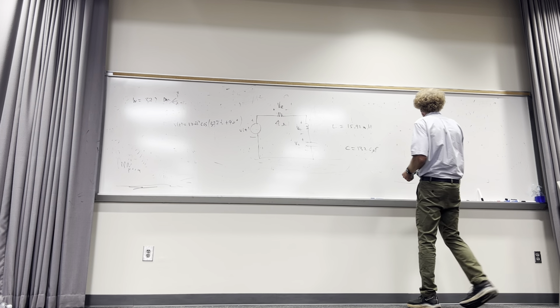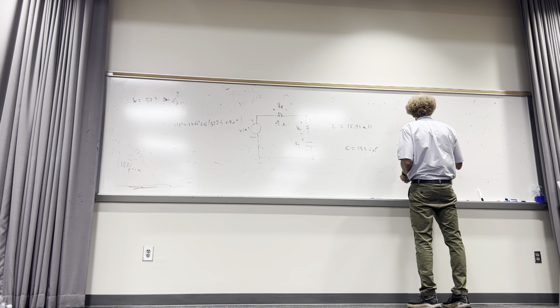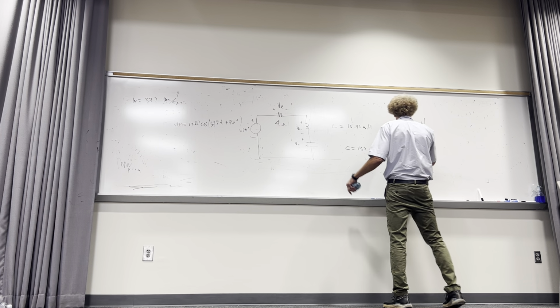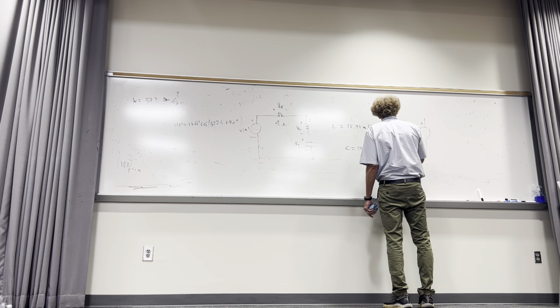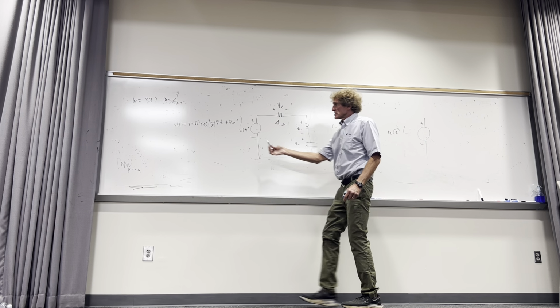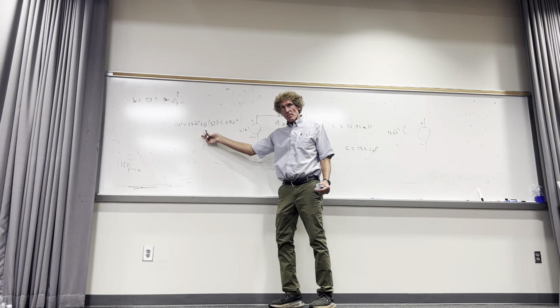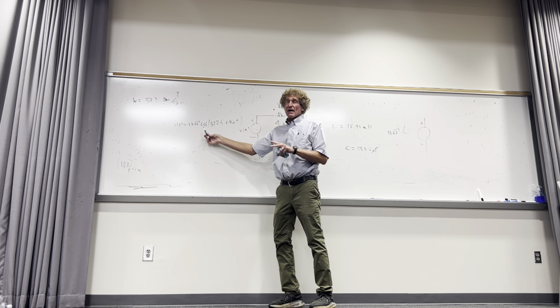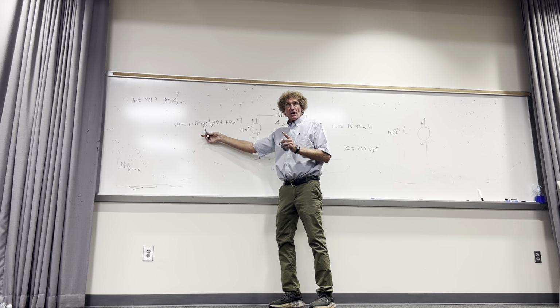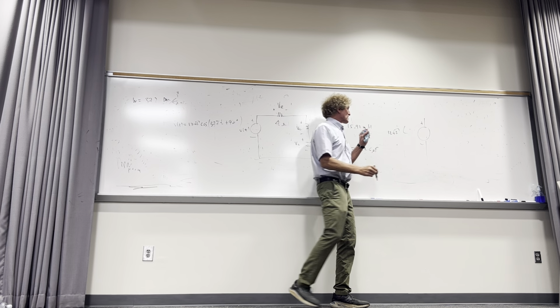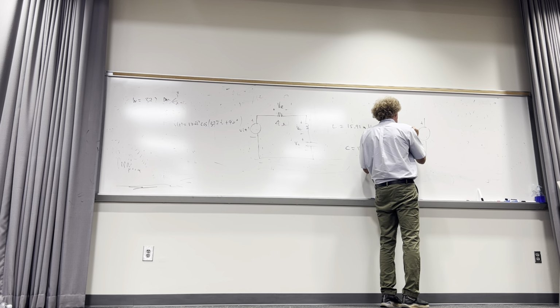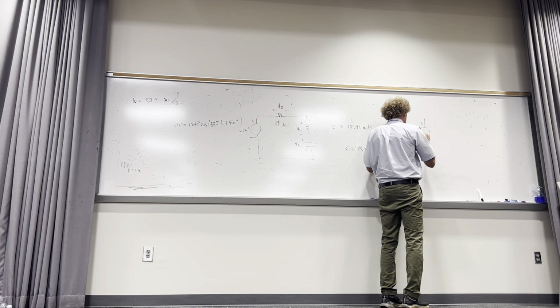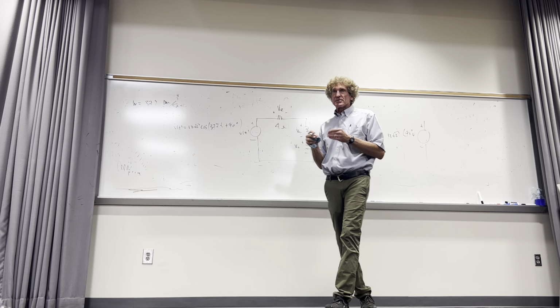So now I go ahead and I put down, now pay attention to this. This voltage has the magnitude of 12 square root of 2, but the angle, see, it's always going to have a cosine form. If it has sine, we'd have to adjust it by 90 degrees, but don't worry about that. We're not going to fool you. That angle comes over here. So this is going to be at an angle of 90 degrees volts. Now that's in the frequency or phasor domain. Y'all with me?